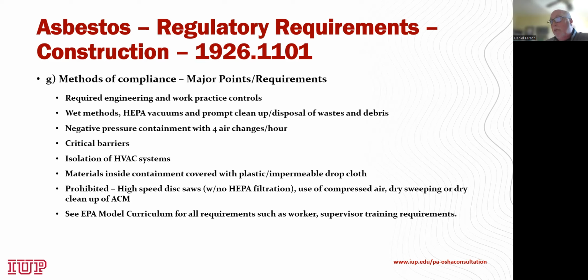You have to set up critical barriers over certain parts, like an HVAC system and windows, and you have to isolate the HVAC systems. The materials inside containment that are just going to be left alone, maybe furniture or things like that, have to be covered with poly or an impermeable drop cloth.